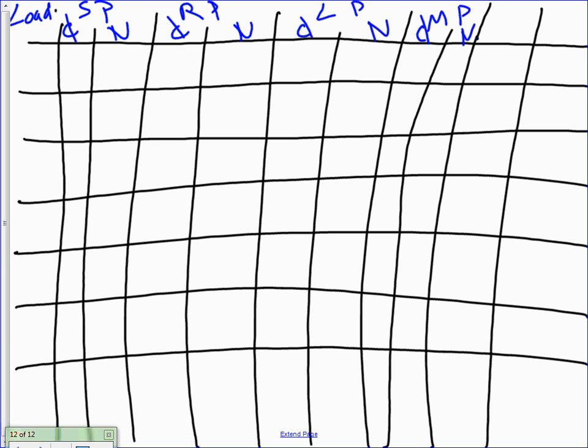So, let's start by putting the load. Load number 1, A. You guys remember load? The first load is A. A was the receptacle load. Can you guys get me the receptacle load, the total for A? Because I think it's different than what I have here. What is it? 56.9. So this will be 56.9. Since this is a receptacle, all of them are going to be sent by the neutral, right? Yeah, because they want one. So also under the neutral is going to be 56.9.